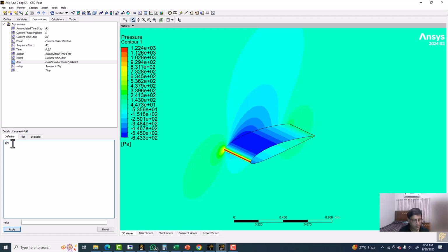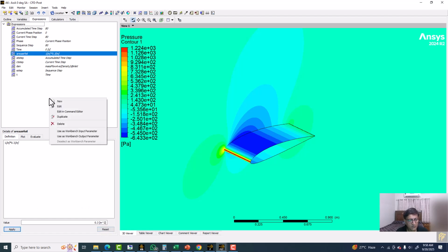Put the square bracket, and once you have the correct units, they will be converted into italic fonts. Okay, you can see it. Multiply with the asterisk symbol, then 0.3, and then again put the units of meter and click apply. This should give you 0.3 and the correct units, which is meter squared.